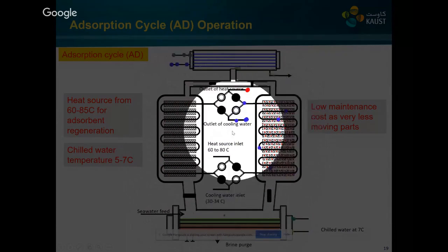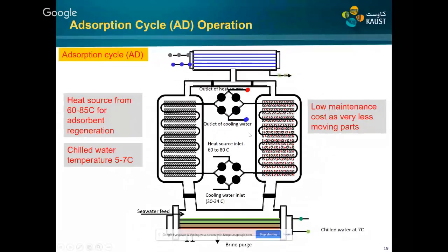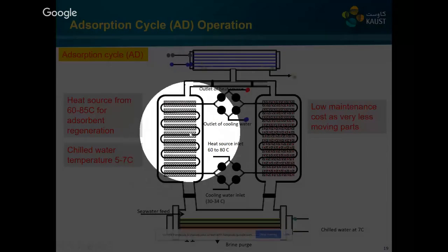In this batch operation, the size of the silica gel and the beds depends on the size of the MED system, and there are no scalability issues because it can be in the form of big silos, and the silica gel can be dumped into the big silos for the adsorption and desorption process. And interestingly, if we see over here, most of the parts are actually stationary, and there's no moving part.